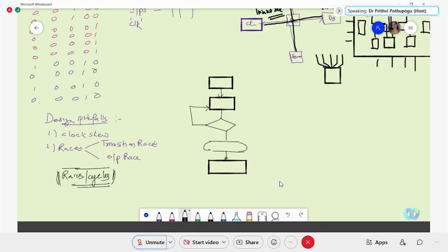It was seen in asynchronous sequential circuits, in state tables where you had y1, y2 state variables. The order of changing, whether y1 changes first or y2 changes first, was introducing a race called a critical race or non-critical race. You remember that?